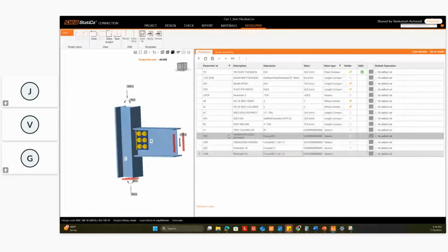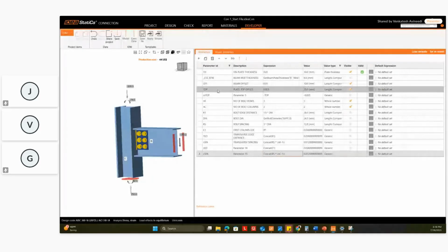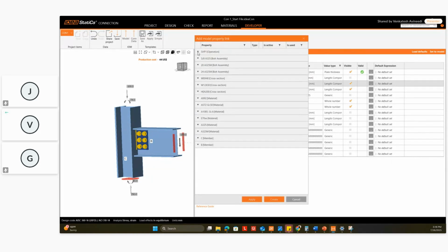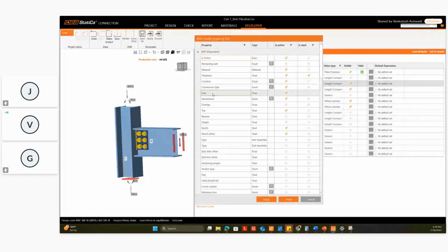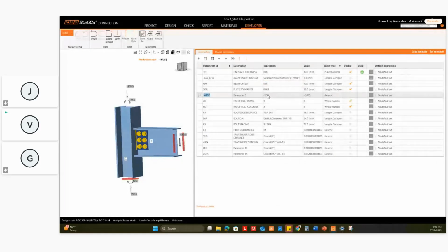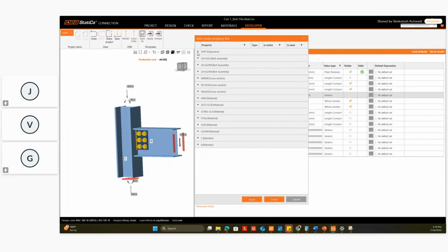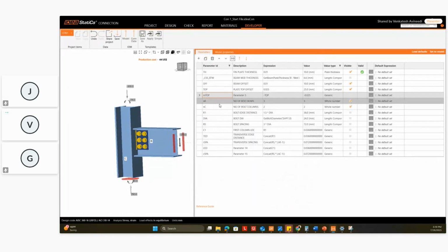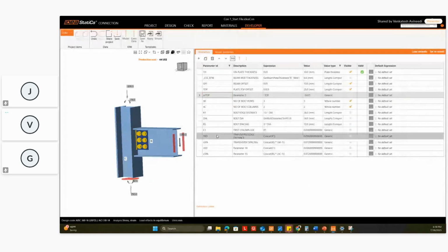Okay, let's link it with the model properties. First, I will link it with the offset. I will go to this option here to link the model property. I will go to SHP1. You can see the setback was given with the gap value in the operations. So select that and create it. And the next one was the top control, which is this negative value. Again, link it with the operation, which is top, create, and I have to link the transverse search distance.